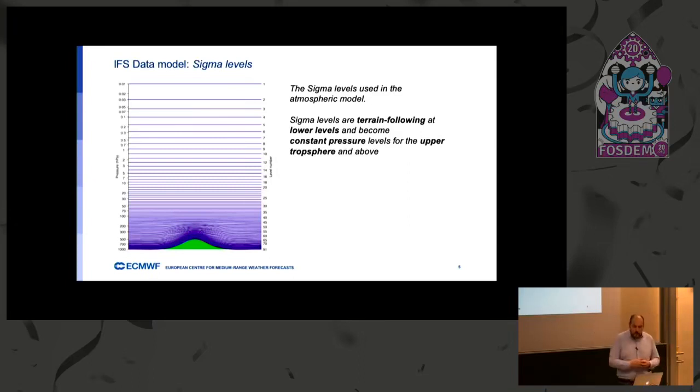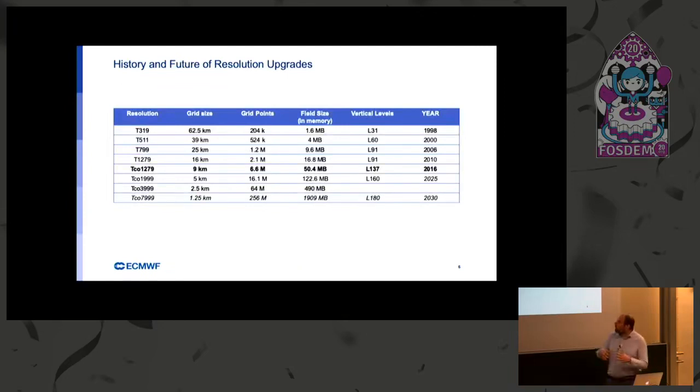Having those constraints, we designed a system that is able to scale with the resolution. So the idea is that we want to provide a higher resolution simulation for our user, but obviously increasing the resolution is quite costly. Doubling the resolution usually costs us 8 times the computational power. 2 for the dimension, 1 because we have to reduce the time step to get accurate calculation. So the impact on the computation and on the output file is pretty heavy.